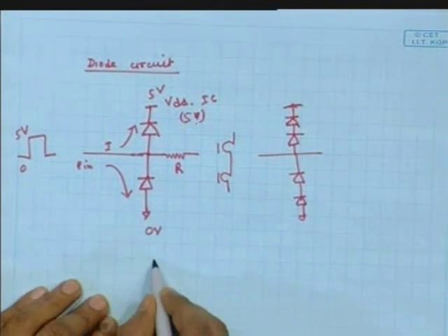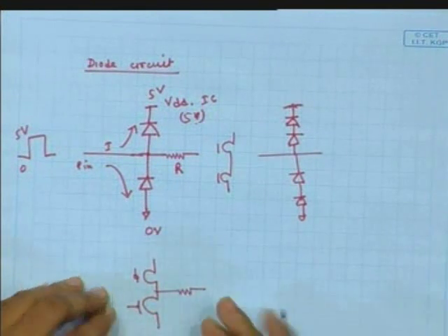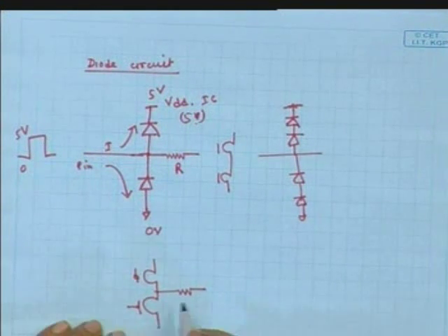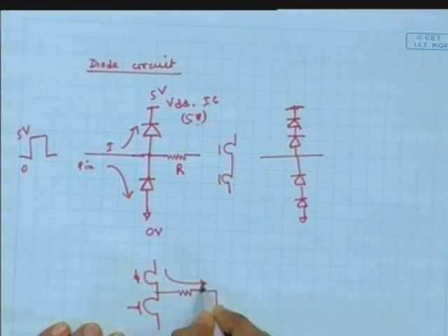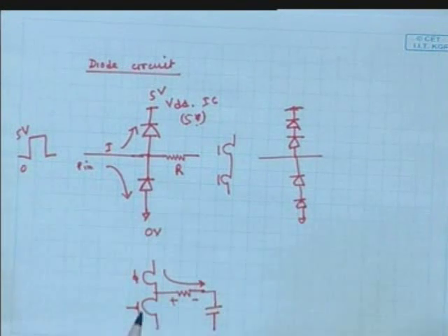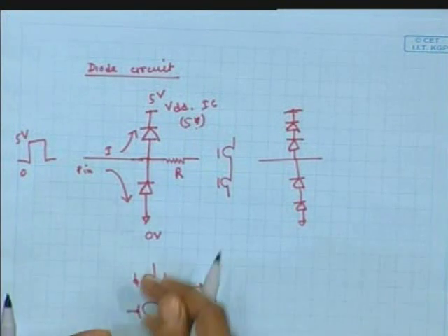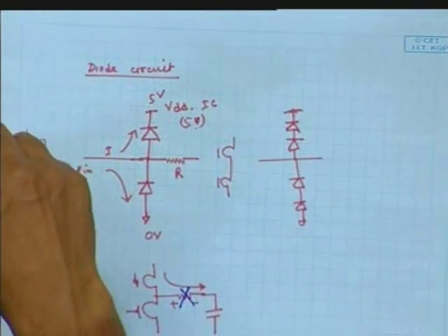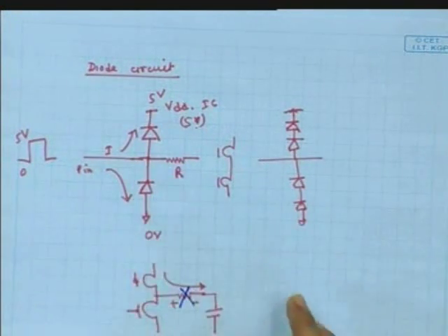Now if you consider the output side, and we add some resistance at the output node to protect the circuit, then when it is charging the capacitance, that means it is driving current, so you get some drop here. So we can't add resistance at the output point. That resistance we can add at the input side, at the voltage signal level, not the current signal level. If current is flowing from the external pin, we can't use the resistance, right?